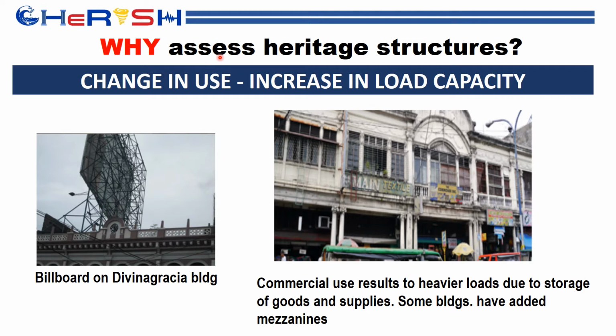Why assess heritage structures? First of all, there are changes in use and increases in load capacity. As you can see in these images, in buildings along the heritage zone in Iloilo, there are buildings wherein billboards were installed. Some commercial use results in heavier loads due to storage of goods and supplies, and some buildings have added mezzanines. Hence, the live load on these structures changes.